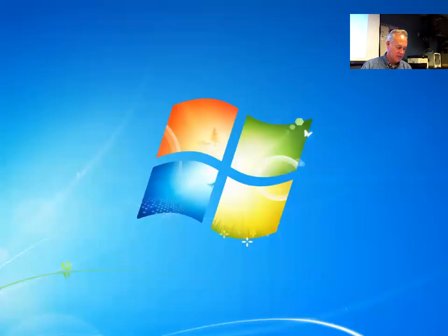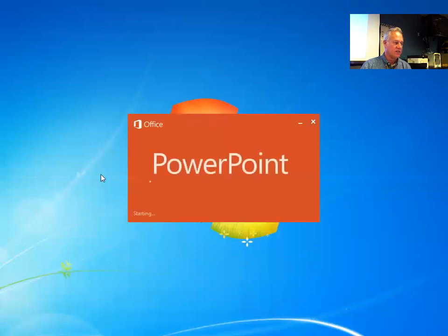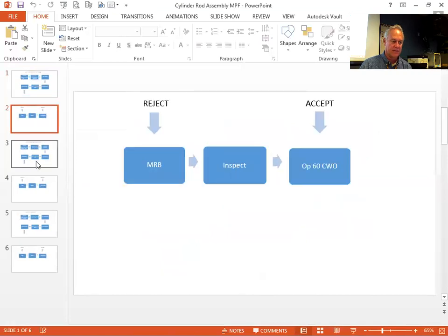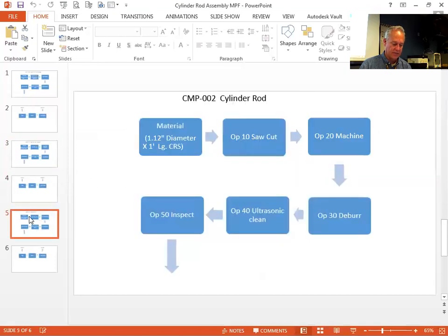Okay? Next thing, our manufacturing process flow. This is nothing more than a PowerPoint that basically follows every step in our bill order of operations in terms of flow. So flowchart software is a nice to have. A must have is a PowerPoint, with the ability to just pop in the order of operations numbers by their descriptions and showing how the process flows in manufacturing. Sometimes operations happen concurrently, and so you have to make that distinction of how the process flows for the assembly, for each component item as well.